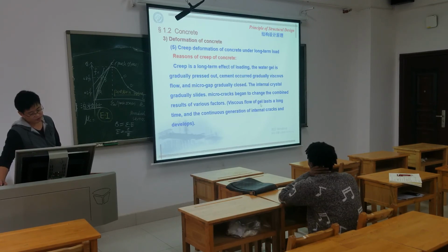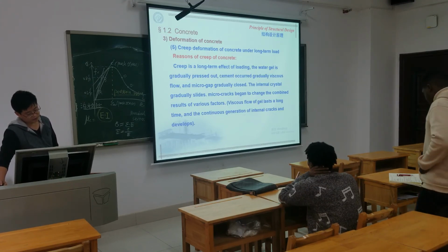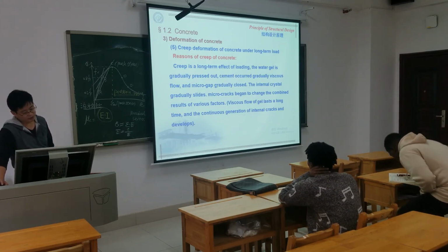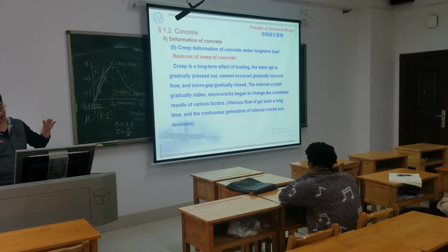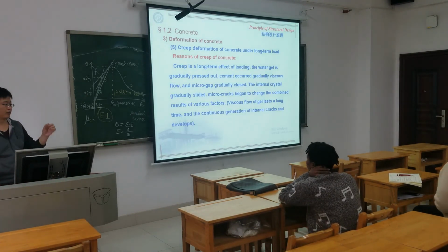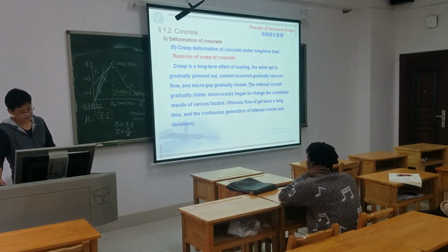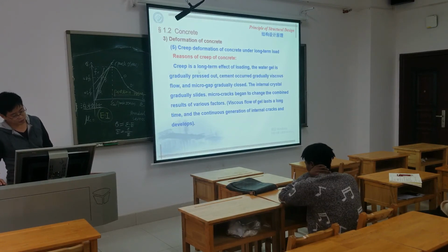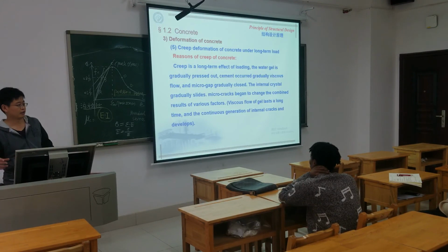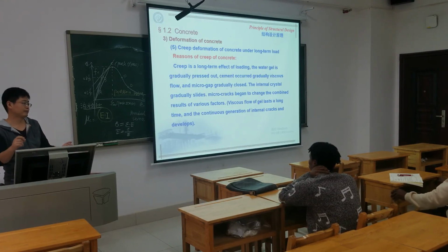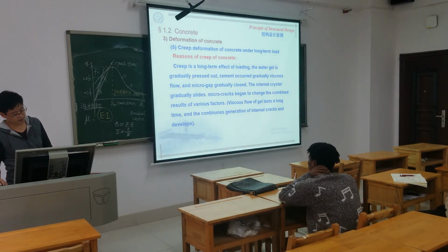Viscous flow of the gel lasts a long time, with continuous generation and development of internal cracks. That means it is induced by internal change, the small cracks or the water gel inside. So this is creep: there's no change of the load, and it develops with time. That's the creep of the concrete.